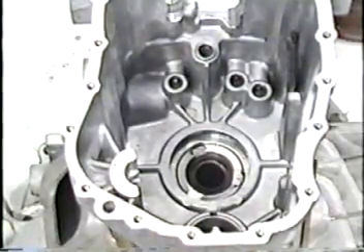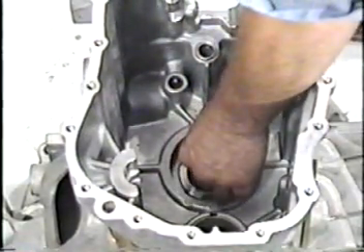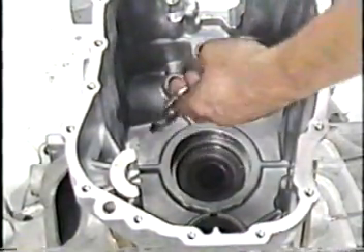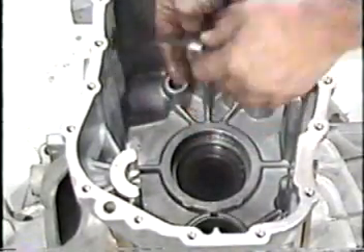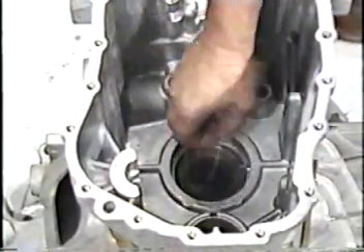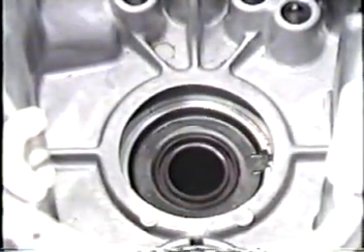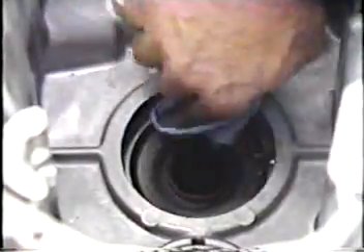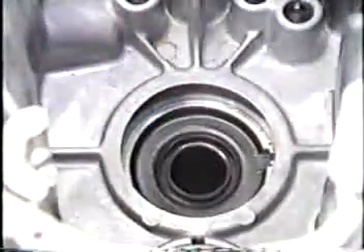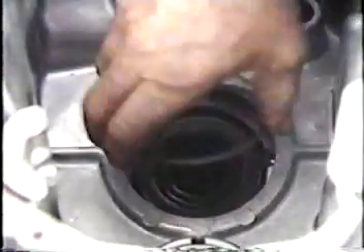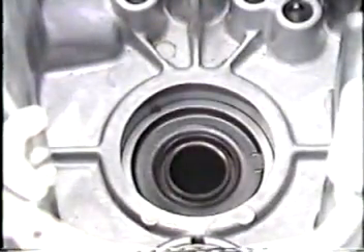The main shaft of the ZF transmission uses an oil control baffle that is installed with the shim. End play of the counter shaft is controlled by a shim alone. After measuring end play on a ZF transmission, make sure the surfaces are completely clean. Then, fit the new shims and baffle plate beneath the outer race. Now finish assembling the transmission.